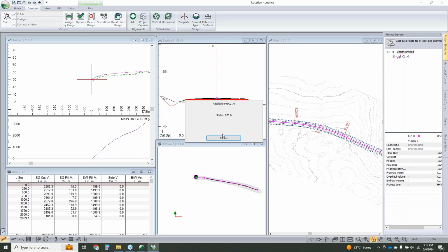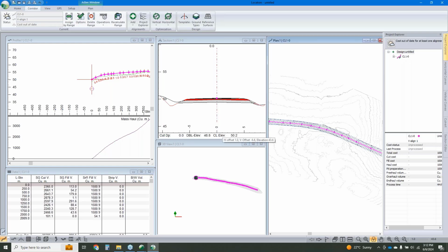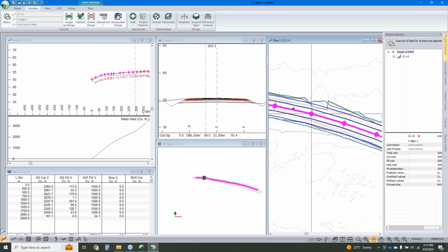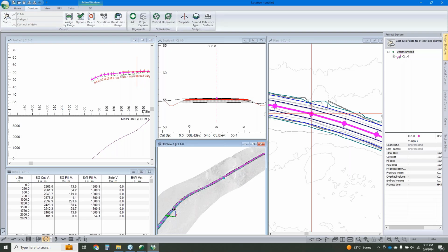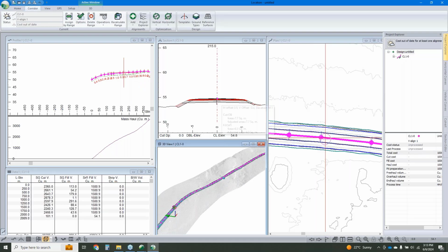is, well, we want to use exactly that surveyed centerline alignment. We don't want to change anything. We just want to make the road, well, repave it and make it a bit wider. So if we want to go that route, we'll just use that surveyed line as we have it. But we probably notice pretty quick, well, we don't want to actually rebuild our whole prism. We don't want to excavate out the existing pavement structure. We just want to do that shave and pave.